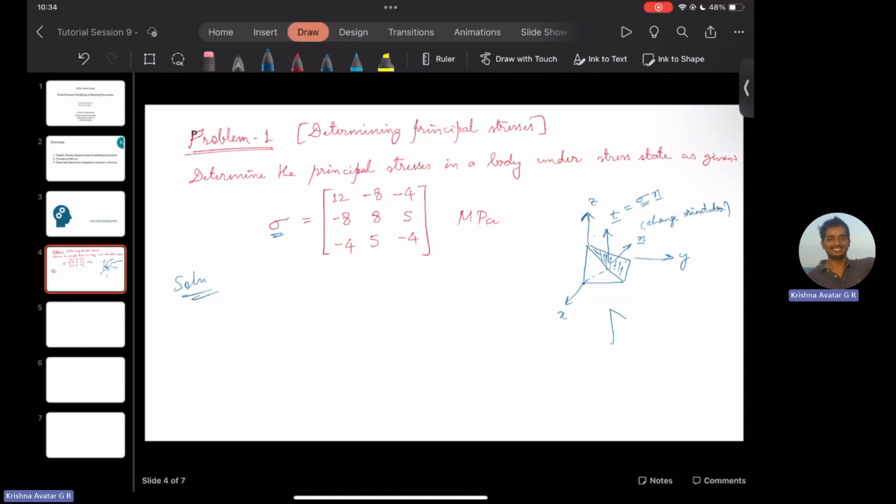Now there will be some imaginary plane, because obviously we cannot just keep on changing, right? It involves a lot of effort and resources as well. So we have this imaginary plane, and t and n may still not be parallel, but we will come across one such plane at which the t vector is parallel to n, which we later call the principal plane.